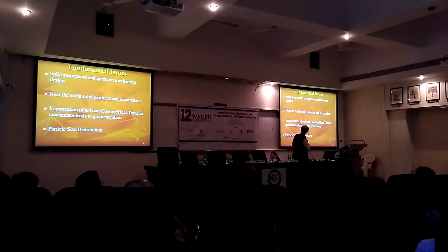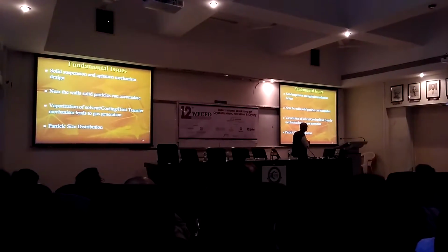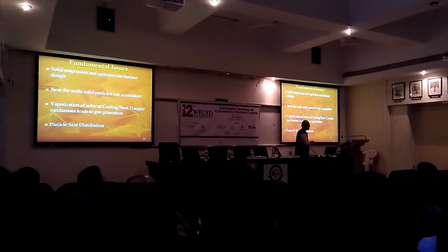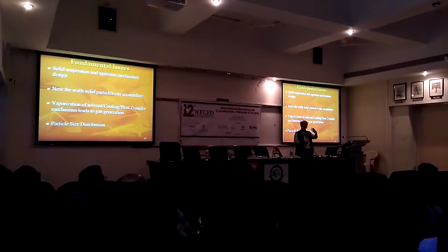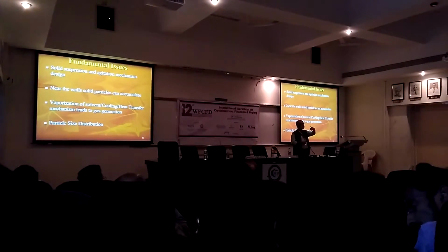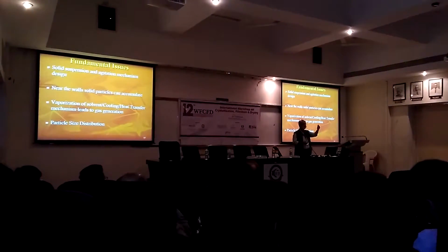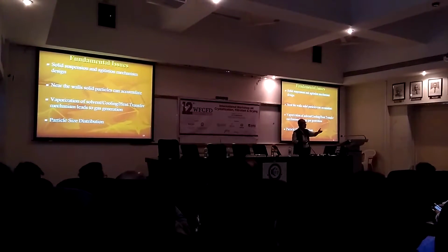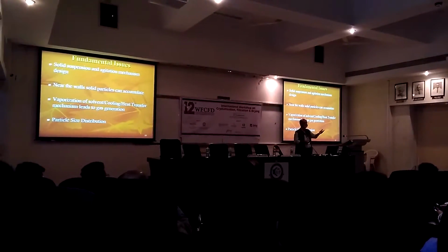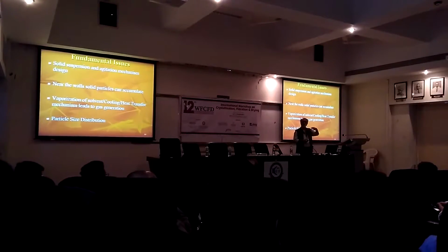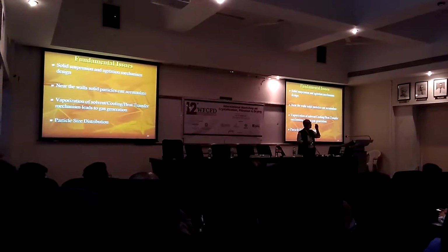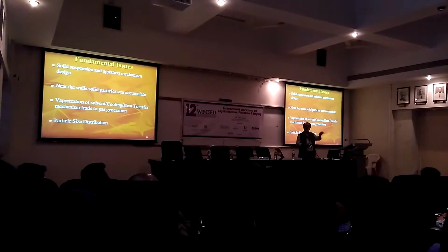These fundamental issues are solid suspension and agitation mechanism required. Second is near wall solid particles can get accumulated because you have a surface which is either cooled or it is hot. If it is cooled, then the maximum supersaturation is going to be created on the cold surface. So the first deposition will take place on that cold surface itself. The deposition of the material on the cold surface will severely hinder the heat transfer coefficient.